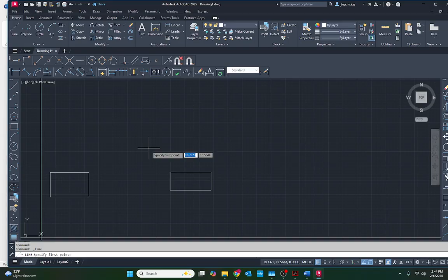However, you generally shouldn't be doing that. You should generally always be typing a dimension. You shouldn't freehand drawings. It's essentially difficult, if not impossible, for me to, let's say, if we look at this line, it's now 24.302 at 9 degrees. Let's say I want it at 24 and 10 degrees. It's virtually impossible to do that. But you can do that by simply typing in coordinates.